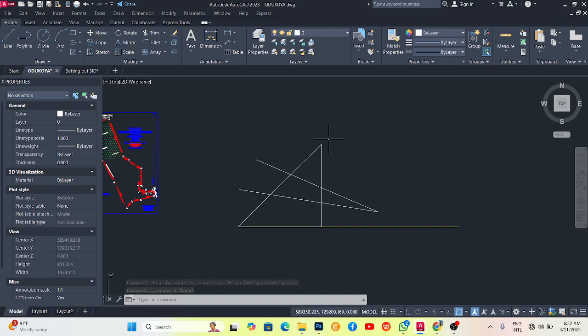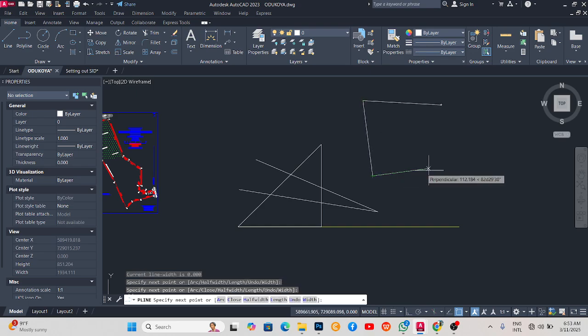And fillet, let's check fillet. So fillet is just F, just type F and you press enter. So what can we fillet? Okay, let me do some polylines. PL, enter. Let's say I have something like this, like this, like this, and I want to join those two angles together. I want these two angles to meet.